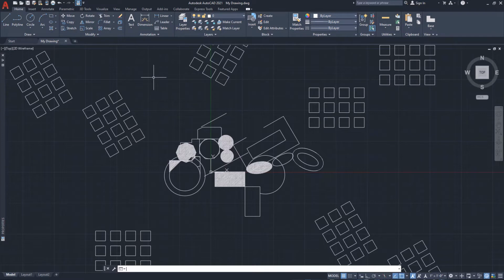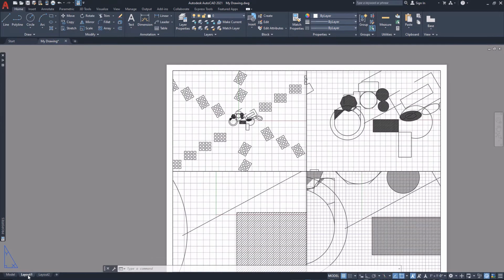Whereas annotative scaling is the mechanism that controls or manages the visual sizing or resizing of annotative objects, the drawing scale at which our objects are displayed on the printed page is assigned to viewports, also known as viewport windows, and are an integral part of our page layouts. We access our page or paper layouts via the Layout tabs at the lower left portion of our display.